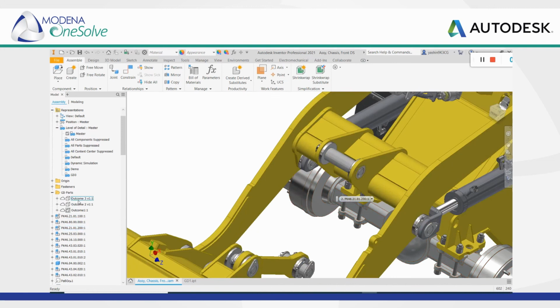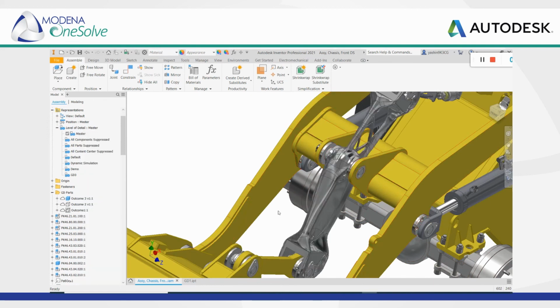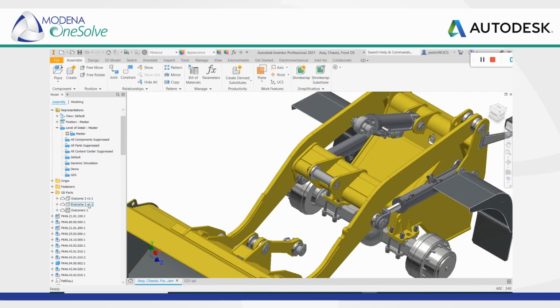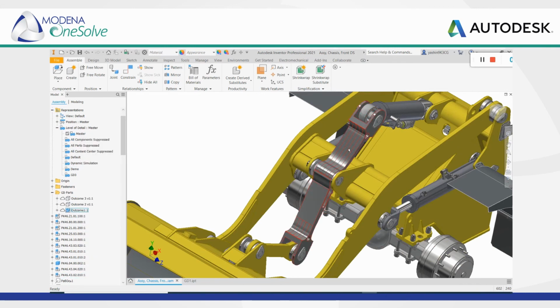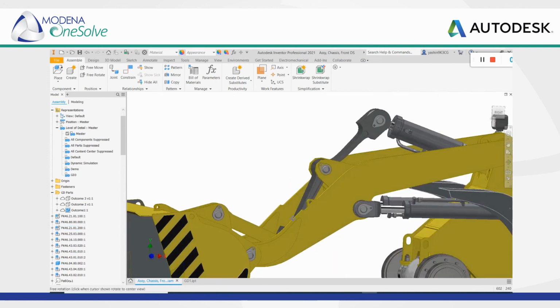And now we can explore all those different design options, while still maintaining the performance objectives of the actual arm. So I'll turn the visibility of this one on, and you can see we have the generative design version. We then have the 2.5 axis machining option. Generative design will give us more than one option, hundreds, thousands, that meet our manufacturing and performance criteria. It has a host of benefits as explained earlier.